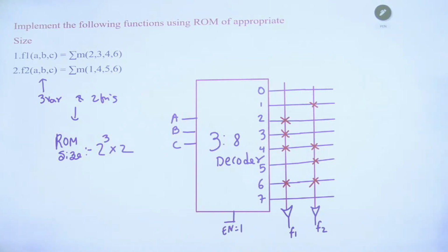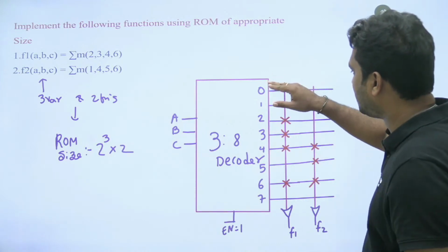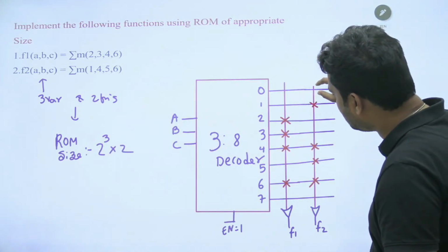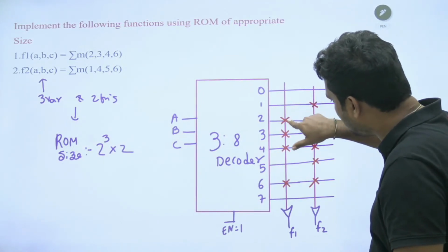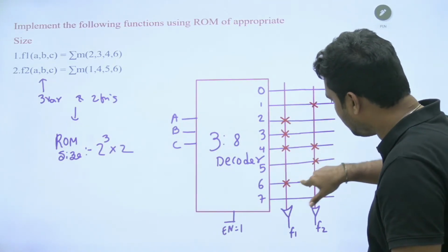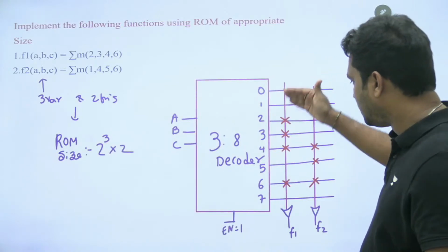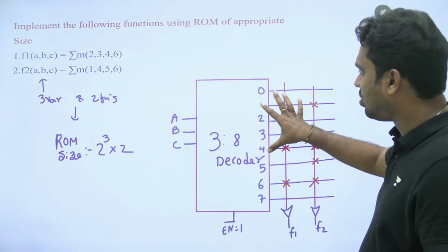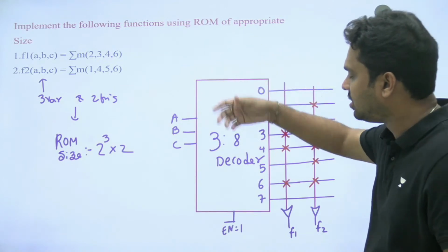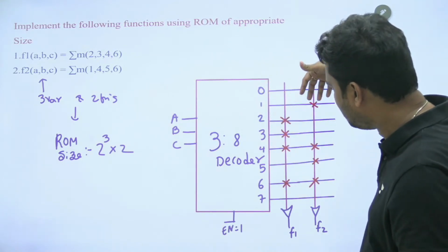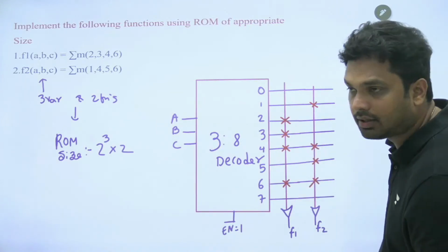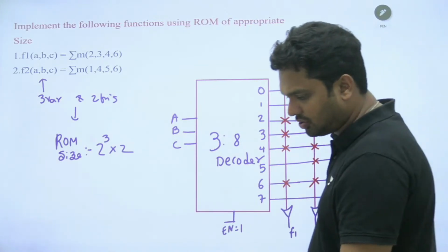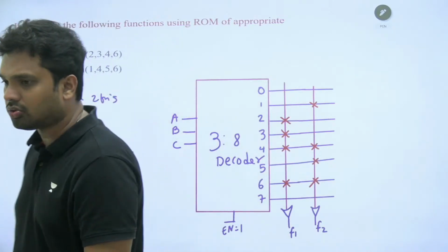Okay. So when a particular line is activated, here nothing is connected, so 0, 0. Here this is connected, so 0, 1, 1, 0, 1, 1, 0, 1, 1, 1, nothing connected. So that will give you the required output. This is the implementation of the functions. It is nothing but taking an OR gate with 4 inputs at a time. From each node, you get one connection to the OR gate. So that is how you implement the functions using ROM, or you can use it to store the data.